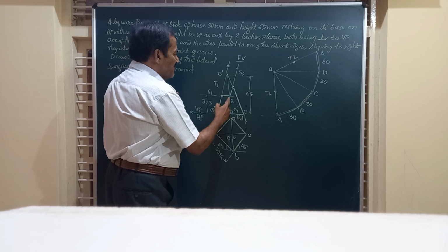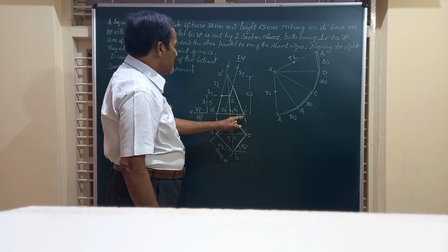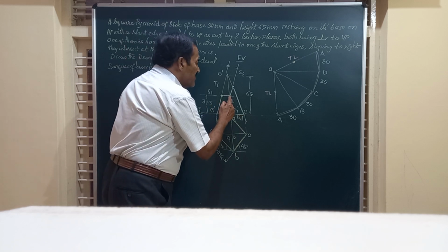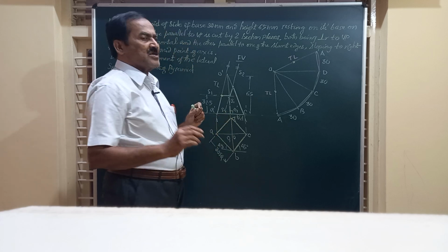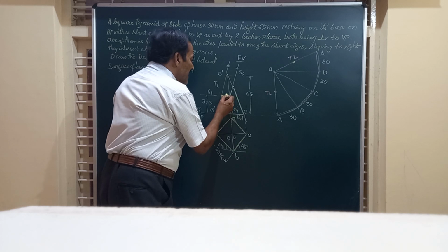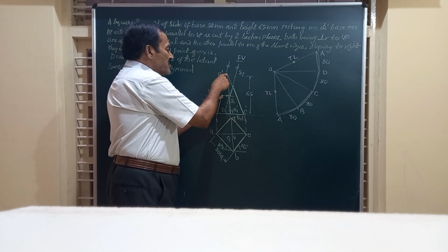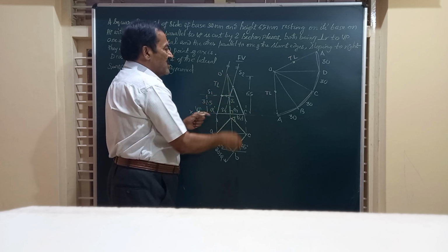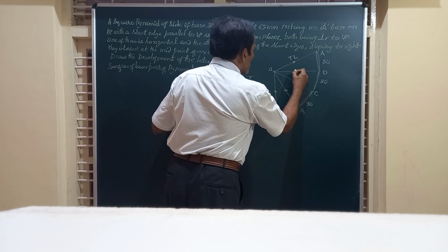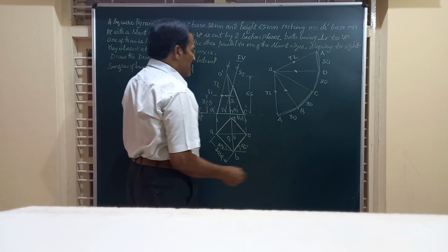So here friends, these are cut here. Where is that? That is exactly in between. That is cutting here. And if you see this OB and OD, they do not represent the true length. Hence, this point has to be transferred to the true length and take that measurement on OB and also on OD. So, both on OB and OD, you are going to have the same measurement. And obviously, this is going to be parallel to the base.